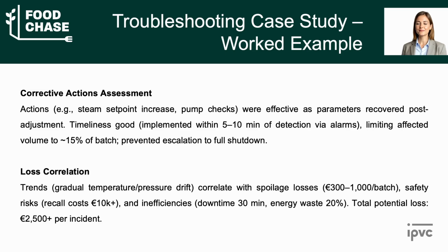Corrective actions: assessment actions, steam set point increase, pump checks, were effective as parameters recovered post-adjustment. Timeliness good, implemented within 5 to 10 minutes of detection via alarms, limiting affected volume to approximately 15% of batch. Prevented escalation to full shutdown.